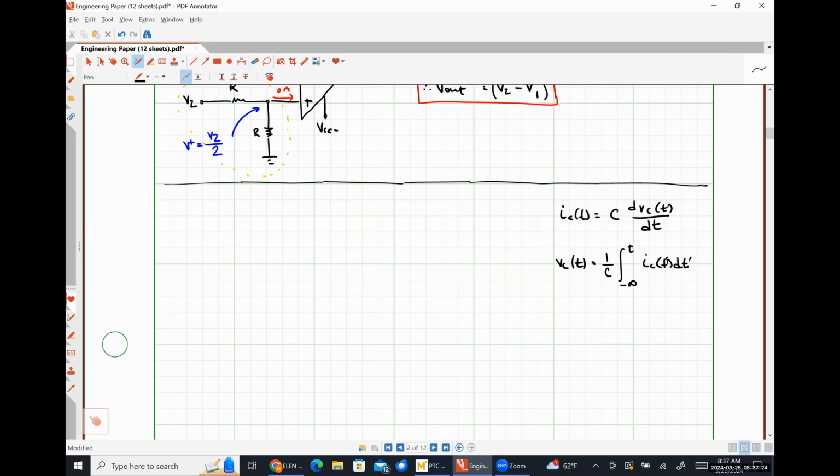So the first one that I want to look at is this circuit. And if I'm being honest, I can never remember which one is which, so we'll give it a name after we see how it works. I think I'm starting with the differentiator, but I might be wrong. So let's put a resistor in the feedback path like so. Let's put a capacitor here.